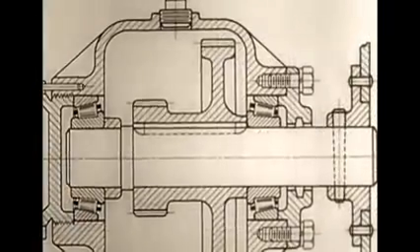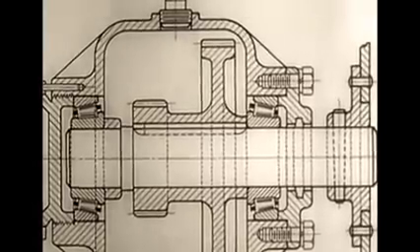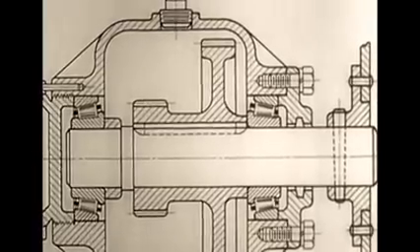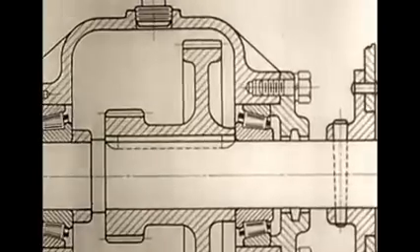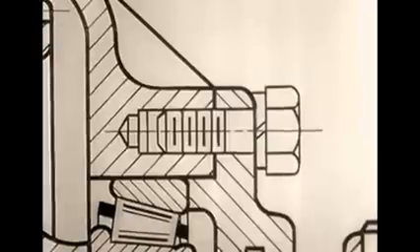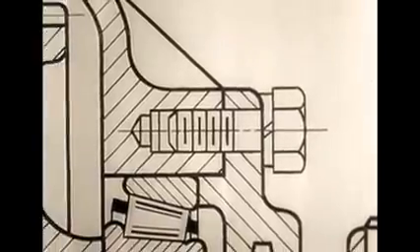As a rule, do not show hidden lines on a sectional view because they would confuse the drawing. Omit them unless they are needed to describe the shape or size of the object. When you show two or more pieces together, the section lines should be drawn in different directions. Space your section lines according to the size of the piece.